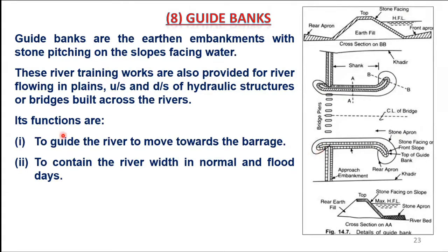Now, what are the functions of these guide banks? To guide, hence the name guide banks. Its function is to guide the river to move towards the barrage. The water that comes here is guided towards the barrage. Number two, to contain the river width.